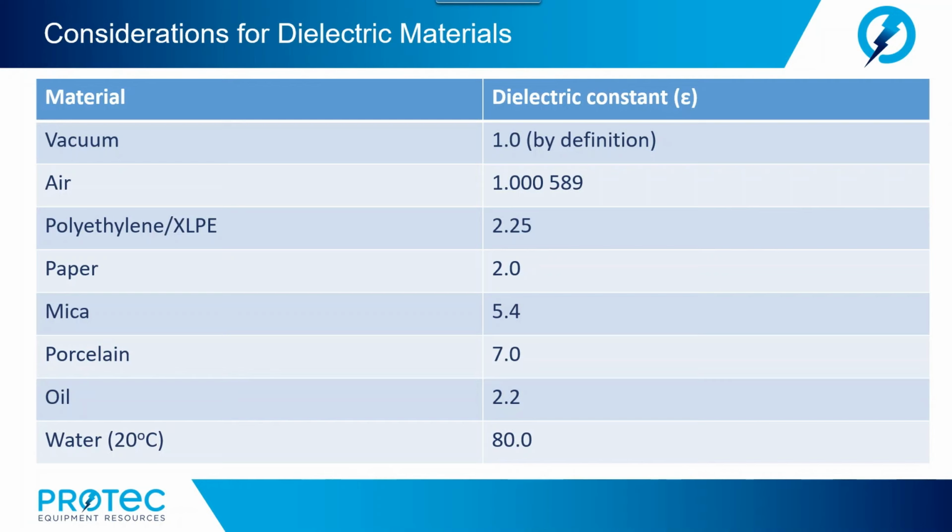Another consideration is the dielectric constant, which is the extent to which a substance concentrates the electrostatic lines of flux. Substances with a low dielectric constant include a perfect vacuum, dry air, and most pure dry gases, such as helium and nitrogen. Materials with moderate dielectric constants include ceramics, distilled water, paper, mica, polyethylene, and glass. Metal oxides, in general, have a high dielectric constant.